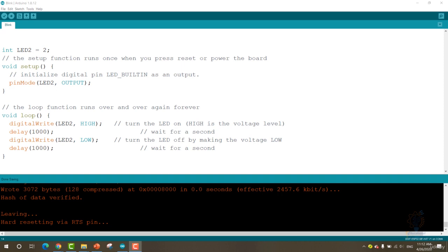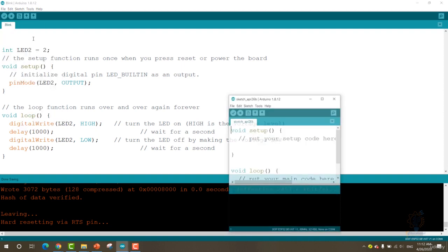We explained these pins in the wiring layout of the ESP32 lesson, but let's talk about them again. These 10 internal capacitive touch sensors can be used as buttons, and they are numbered from general purpose input-output number 4, 0, 2, 12, 13, 14, 15, 23, or 32, 33, and 27. These are the pins. I will show you the pin numbers in a minute.